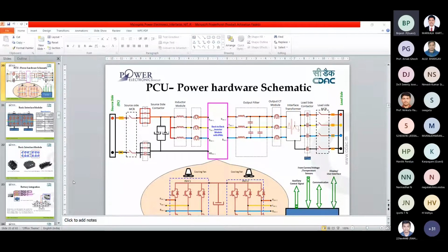There are three parts in the charging of a lead acid battery. First is constant current mode, where you can charge up to 70% of the battery. Then the remaining 30% you can charge by topping charge, that is in constant voltage mode. You can also maintain the battery charge with float charging.